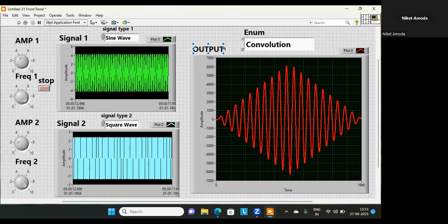For that, you need your laptop to have LabVIEW software. You must have a data acquisition device. In an academic case, it can be an RPi, Raspberry Pi, or an Arduino board. You can have advanced boards like ARM processors or Jetson Nano NVIDIA boards. You connect it to a laptop, and there are multiple read and write channels in those boards: analog read, analog write, digital read, and digital write. You connect your sensor to those ports, and the data acquisition device is now connected to your LabVIEW.